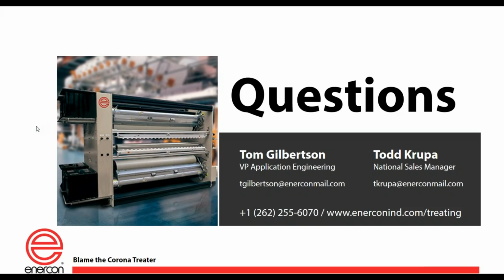Well, that actually is very simple. So I want you guys to think about this. What's a corona treater? What is corona? What is it? Ionized air. Thank you. Corona's ionized air, and if you look at what foam is, what's foam? It's basically all air. Whether it's closed cell or open cell, you've got a lot of air in there. So of course, if it's open cell foam and it's only like a 2 or 4 pound foam, and you turn a corona treater on, you get this discharge, and it's ionizing the air that's in the foam.